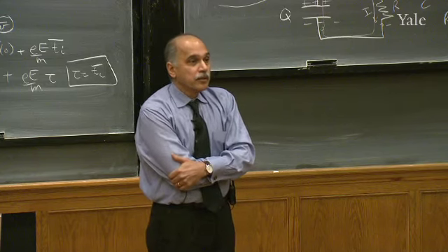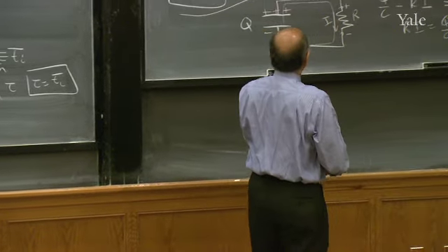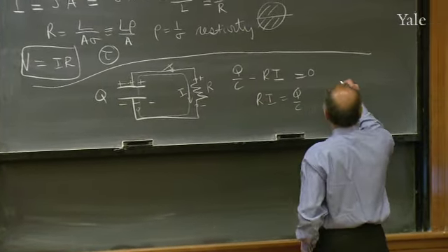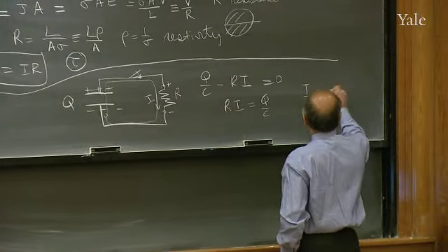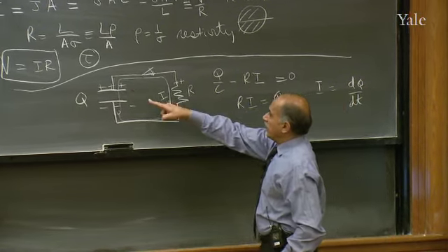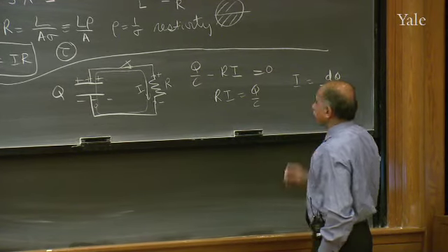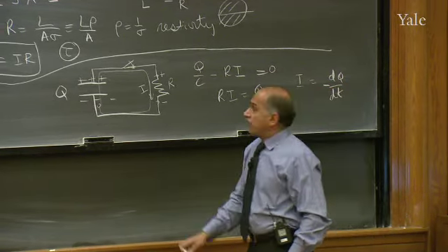It's not necessarily divided by time, but it's a derivative. I is dq/dt, because in a small time dt, when the current I flows, I dt coulombs flow through here, but they've got to come from there. But the only thing missing is the minus sign. Because if I is defined this way and it's positive, a positive I depletes the charge,